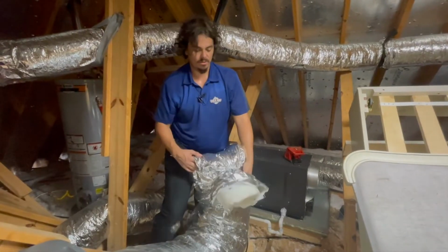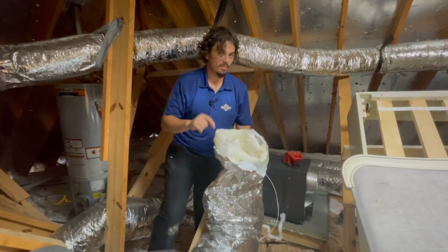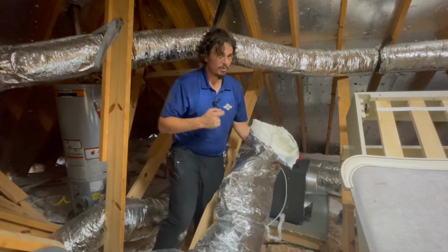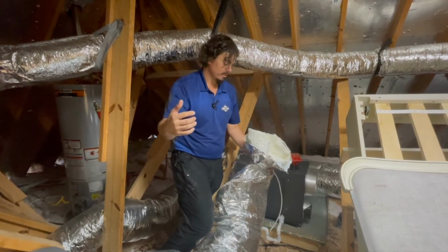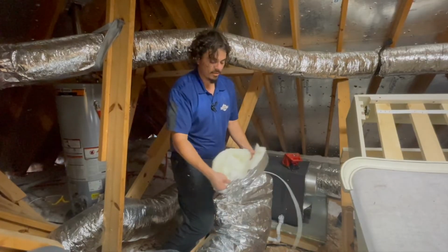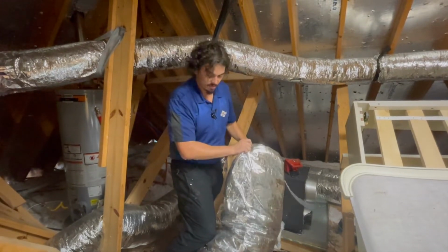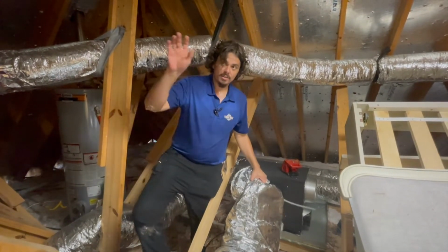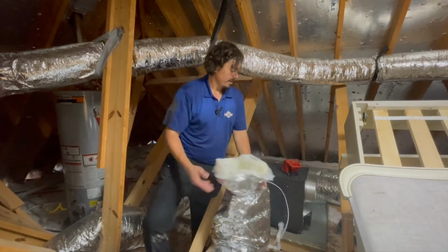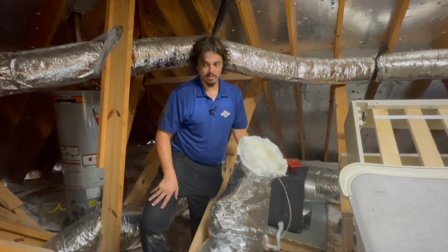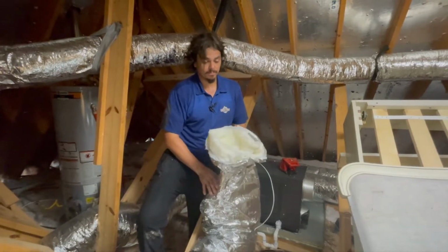However, this duct is that second return air duct that we found upstairs, and it is still hooked up to the piece of equipment. Now that's pretty alarming because we saw there was return air leakage on the main return air duct, as well as leakage occurring through this attempt at sealing by putting a strap on this duct. For that area to still be under negative pressure, even with this return and that return leaking, that's exceptionally concerning. We have some major issues occurring, both duct leakage and building infiltration.